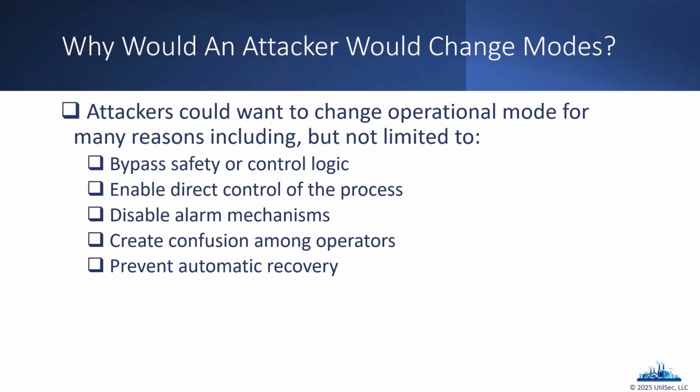Well, what if we disable those? So the PLC knows all these bad things are happening and it's trying to get the attention of the operators, but what if we silence those alarms? So there are no flashing red screens and there's no blaring sirens going off. Loss of visibility. And in a way, it's a loss of control, because the operator needs to take action, but they're not because they don't know they need to.